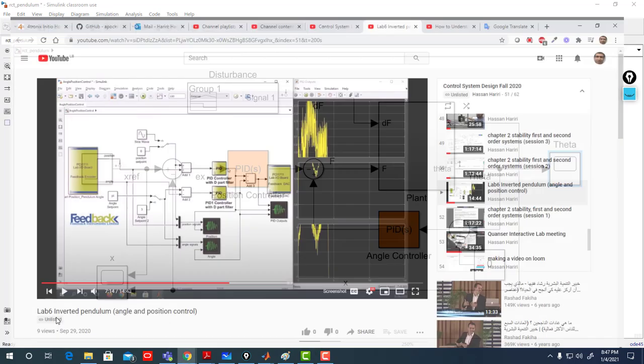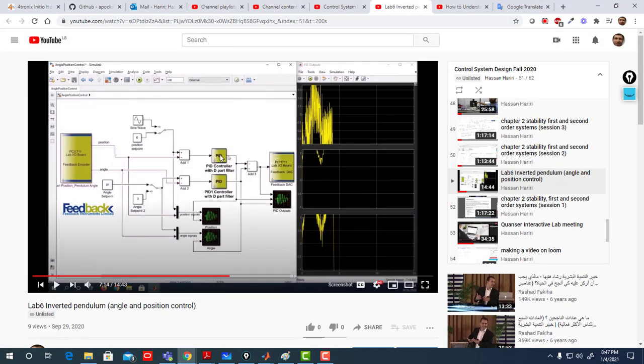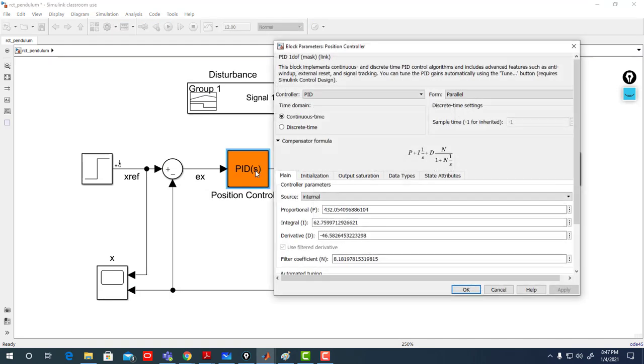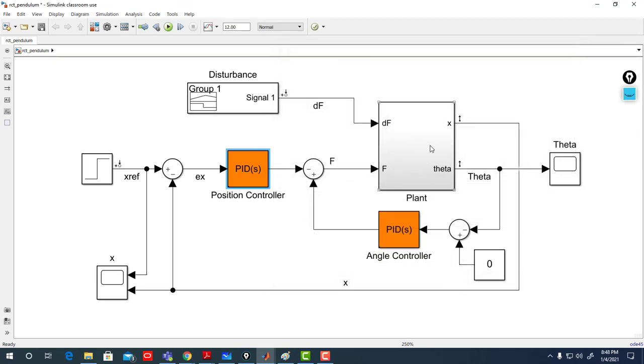So tuning parameters is hard, like you have P, I, D and N, four and four, you have 8 parameters and they could be coupled together. So tuning 8 parameters that affect each other is really hard, experimental. So that's why it's very important to have a model for your system. So knowing the model for your system, you can easily tune it, and have this as a starting point which you can implement in your experimental system. Okay.